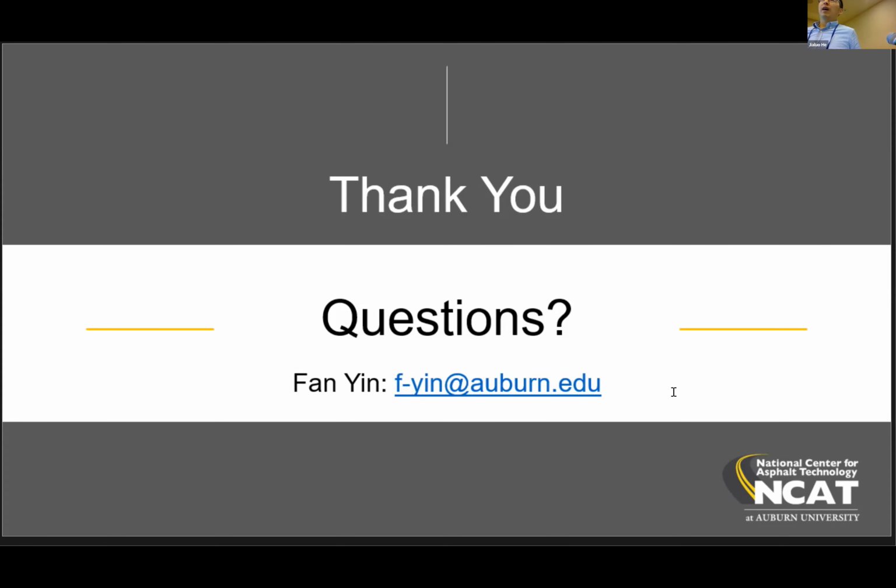Yeah, absolutely. 100% agree. Right now, the way agencies accept RAP is based on binder content and gradation. But as we all know from the research perspective, the binder quality matters. So that's why when you talk about oxidation versus UV radiation and also what kind of base binder you start with, I think that is a knowledge gap that needs to be addressed.